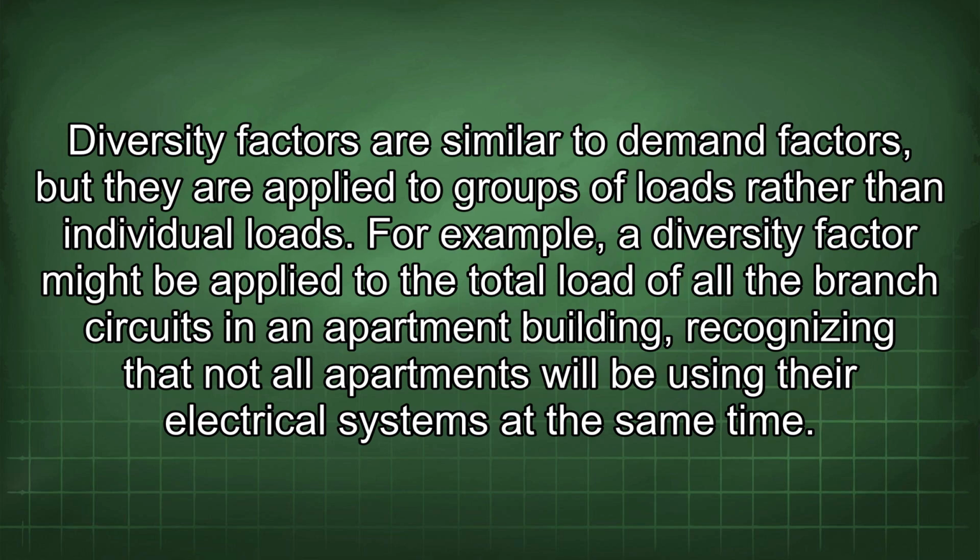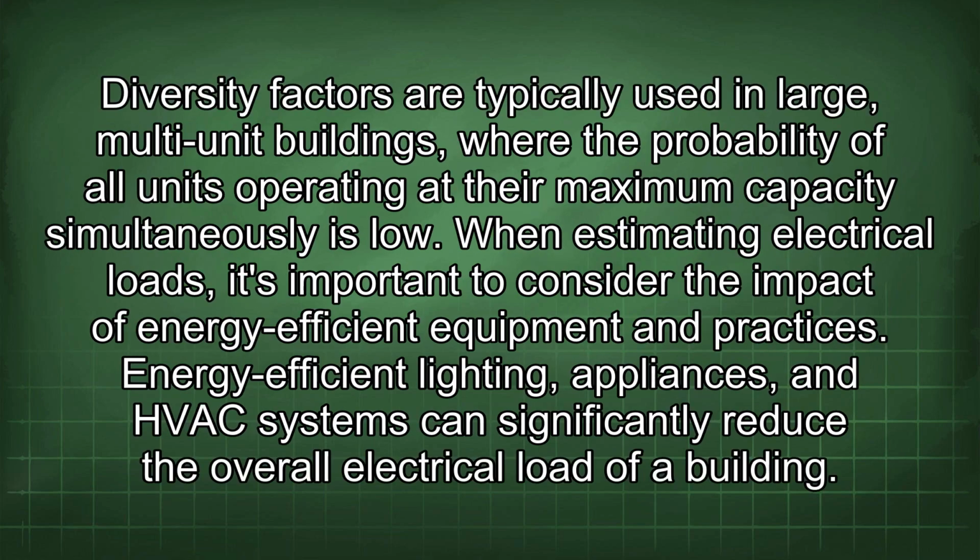In addition to demand factors, the NEC also allows for diversity factors to be applied in certain situations. Diversity factors are similar to demand factors, but they are applied to groups of loads rather than individual loads. For example, a diversity factor might be applied to the total load of all the branch circuits in an apartment building, recognizing that not all apartments will be using their electrical systems at the same time.